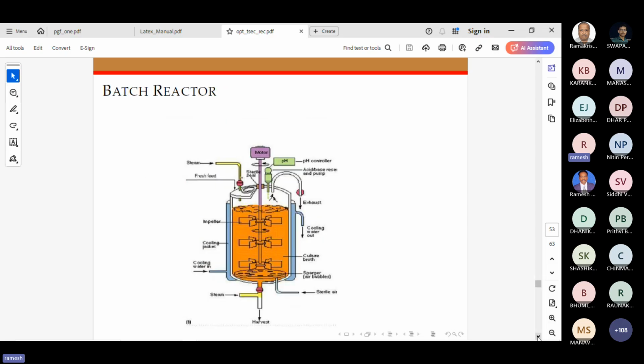The other problem is a semi-batch reactor. In this case, a batch reaction initially starts with one component. The other component is fed as a fresh feed at a particular flow rate. So basically the flow rate is to be sent in as a function of time. If the semi-batch operation takes place over, say, a batch time of 2 hours, how will you decide what the feed flow rate of this second component into the batch reactor should be over those 2 hours?